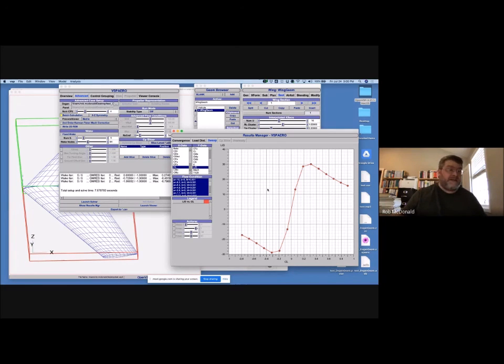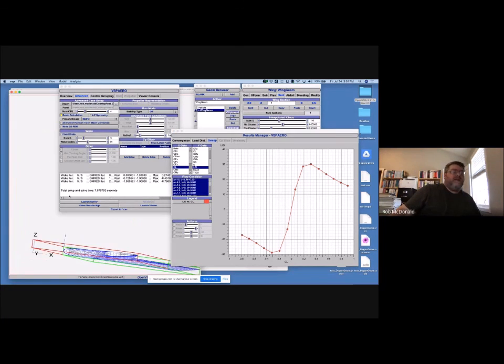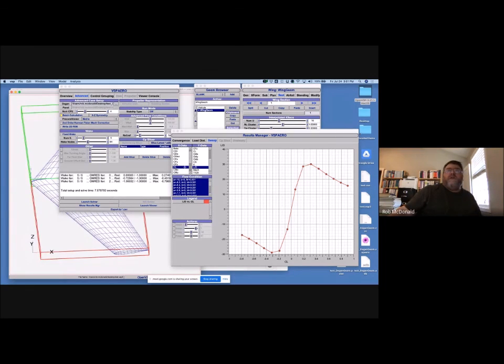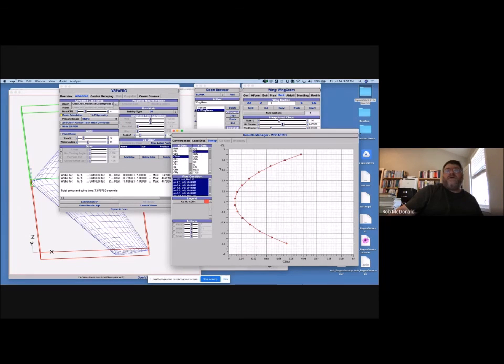And let me just give you an example. On a very clean airplane like this, on something like a blended wing body or a flying wing, if you have fixed landing gear, and so your wheels and your struts are all hanging out in the air for the whole flight, that fixed landing gear probably doubles your drag. Okay, it's huge. And I don't know if you noticed, but do you see any landing gear in this model? Right, there's no landing gear. So when we look at our drag polar on this airplane,